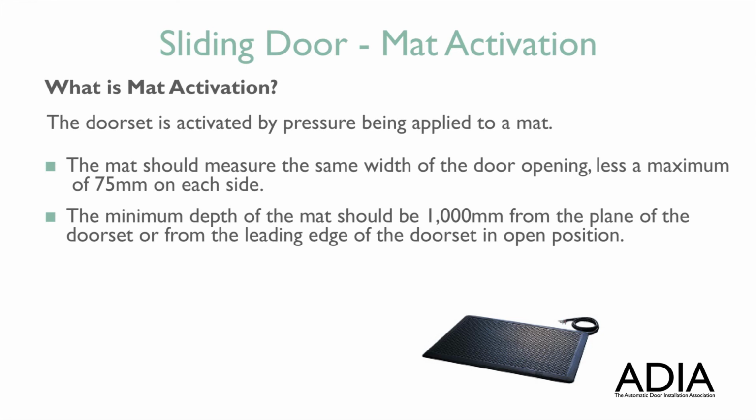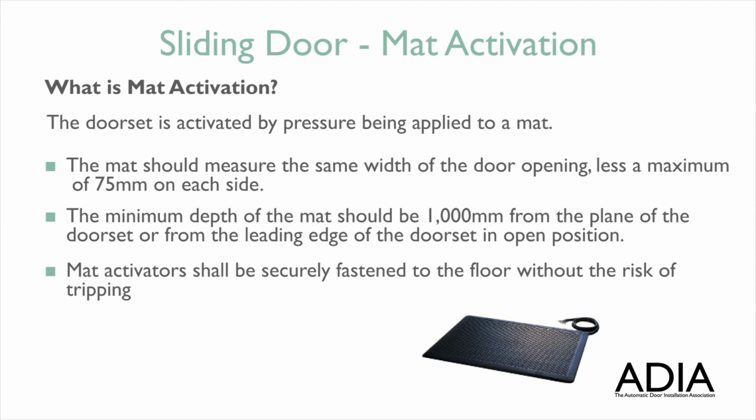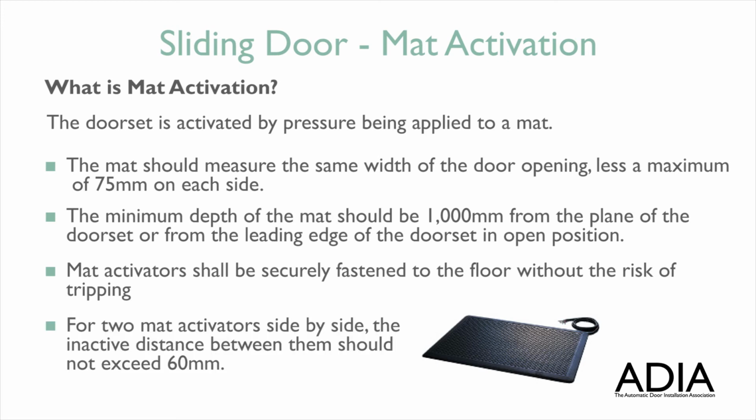The minimum depth of the mat should be 1000 mm from the plane of the door set or from the leading edge of the door set in open position. Mat activators shall be securely fastened to the floor without the risk of tripping. For two mat activators side by side, the inactive distance between them should not exceed 60 mm.